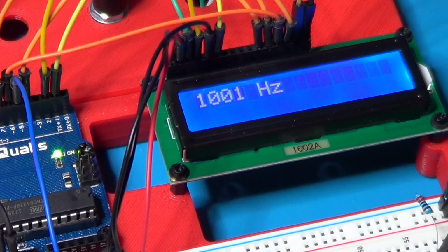So let's start trying with 5 kHz. And yes, this version of the frequency counter still measures it quite well. So let's go now to 10 kHz. And look at that, we are still fine, and the measurement is accurate to better than 1%, which is great given the simplicity of this circuit. I am at 50 kHz now, and the reading still has a precision better than 1%, and it is very stable, no considerable flickering. Let's go now to 100 kHz, and again we have a good reading with a precision better than 1%.